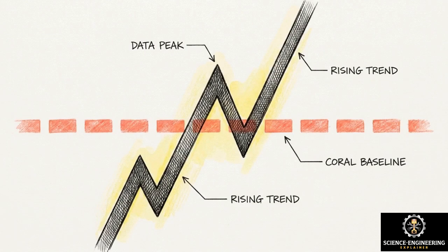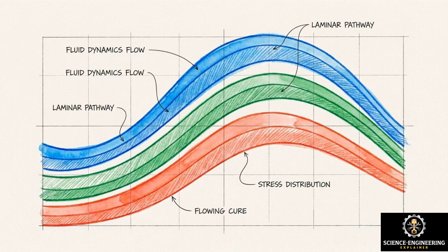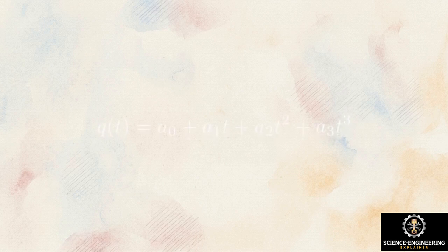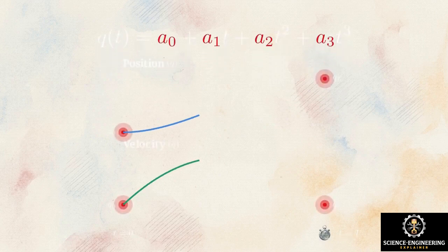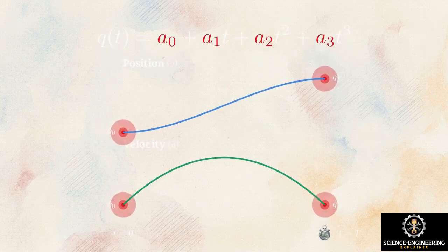To guarantee safe physical execution, bounding the maximum values is not enough. The position, velocity, and acceleration functions must all remain mathematically continuous from start to finish. To achieve that continuity, trajectory planners use polynomials. The cubic polynomial is the foundational equation used to ensure continuity across both the position and velocity outputs.